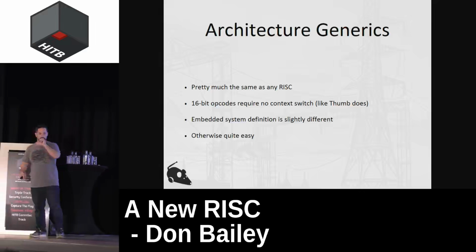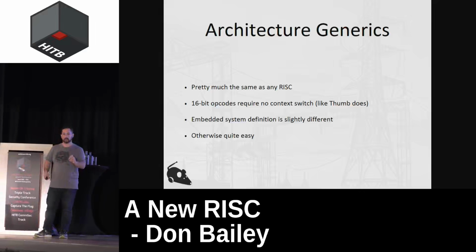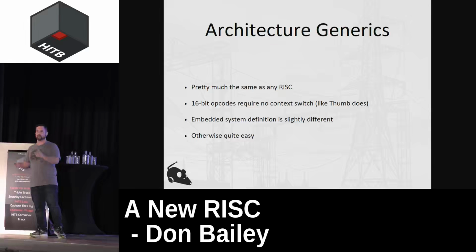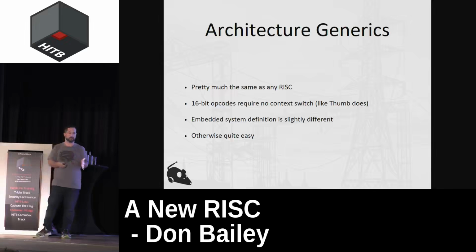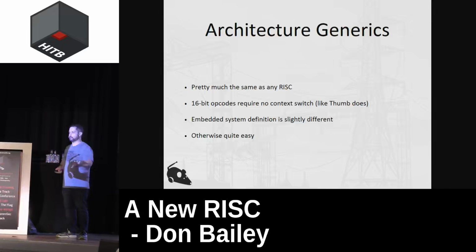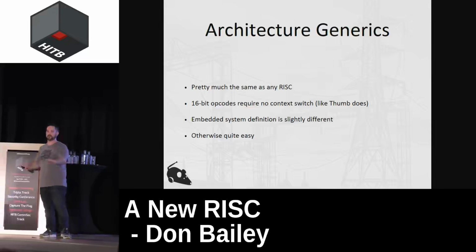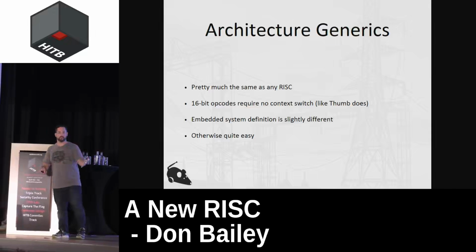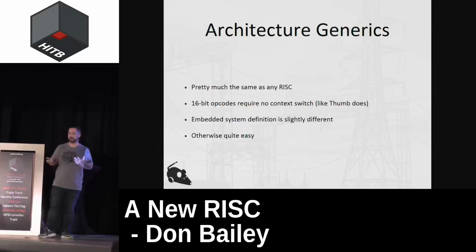But more importantly, it's really cool from a cost perspective, because if you want to further beat ARM in development of something similar to a Cortex M0 Plus or even a Cortex M4F, you can reduce almost half of your silicon cost by implementing the embedded variant of the RISC-V architecture, which is 32-bit only, but if you're building those kinds of microcontrollers, you really don't care. That's not necessary. So that reduces your costs even further, which is why, to me, RISC-V is even more exciting.